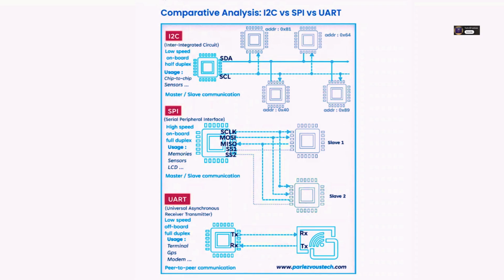Okay, so I²C's 2-wire multi-device thing is a clear win over both SPI and UART in certain situations, especially for saving pins and wiring. What about speed and that synchronicity you mentioned? Speed-wise, I²C is generally slower than SPI. SPI often gets higher throughput because it has separate data in and out lines, allowing full duplex, and often runs at higher clock speeds.